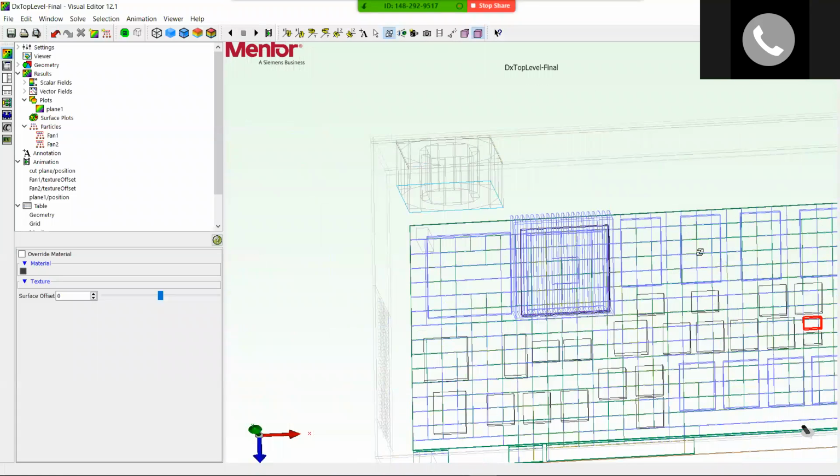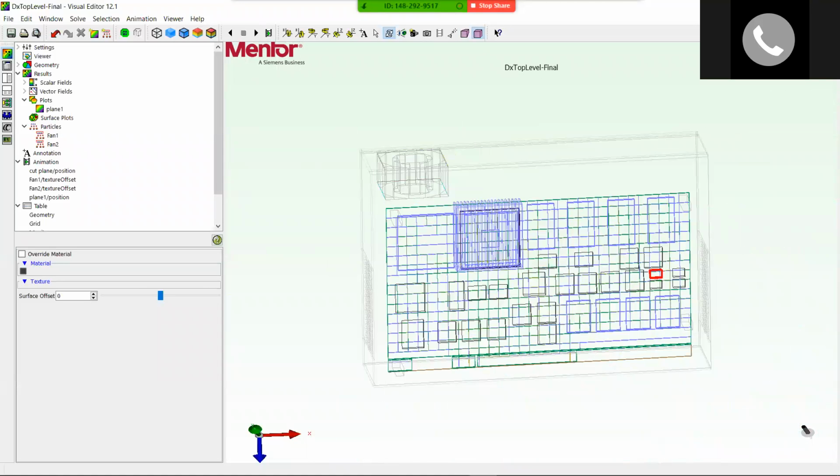There are many solutions to this problem. You can move the fan to here, okay? That will be in line with this. You can move the heat sink horizontally, rotate it, and then that will be in line with the vent, okay? And the fan could be over here, but you can't just move the fan around any way you want, because you may have a restriction in real life of where the fan can be, where the AC plug might be, so all of that stuff. But to answer your question, there isn't one optimum location of the fan. Okay? There can be many optimum locations.